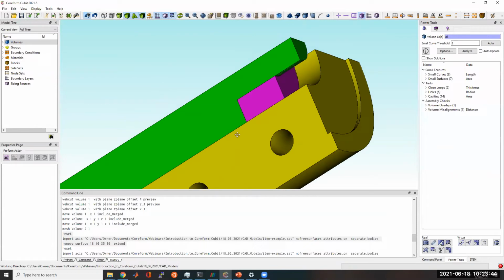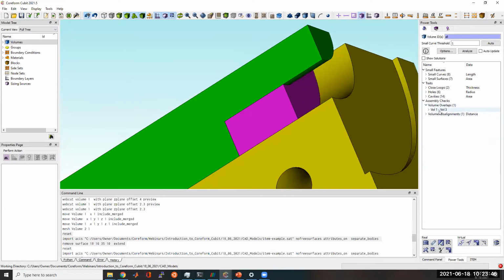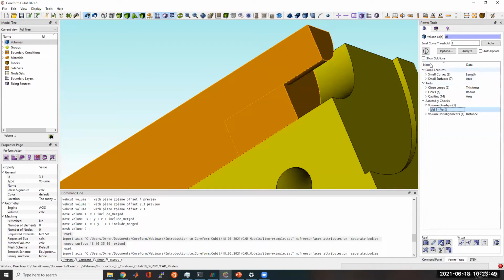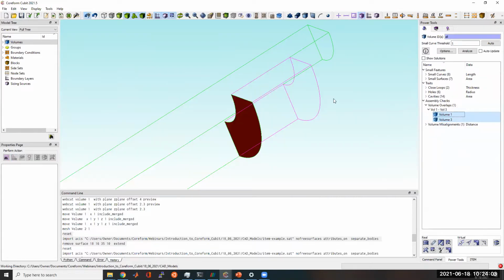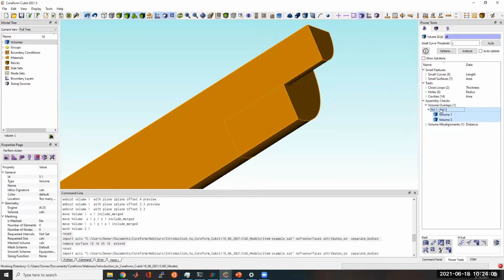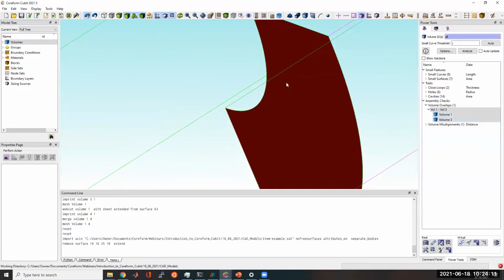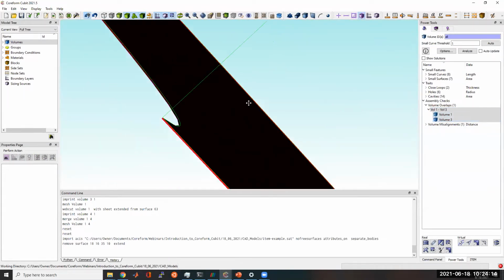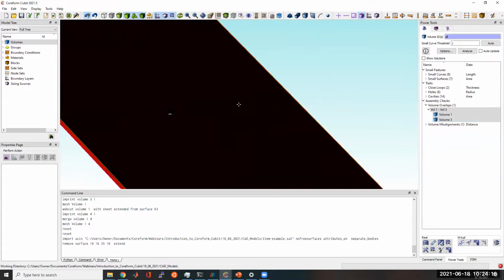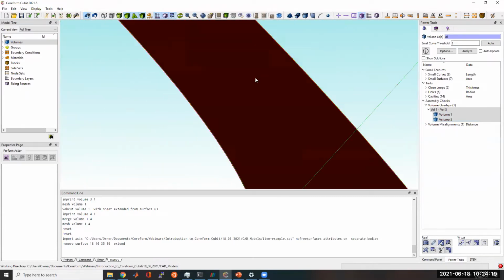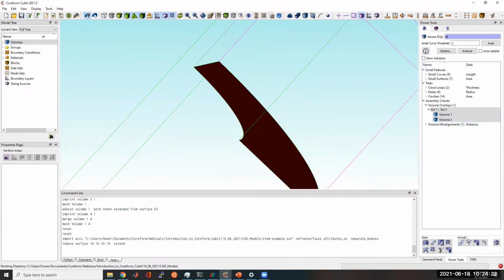And actually, this overlap, we can see here, it's found between volumes 1 and 3. So for all of these, I've got these different warnings it's giving me, but specifically for these two volumes, I've got this overlap. And I can draw this volume overlap by right-clicking on this pair. I can draw the volume overlap, and then we can see that there's this little region that's been overlapped. And so that gives me a hint that I'm going to want to fix that.